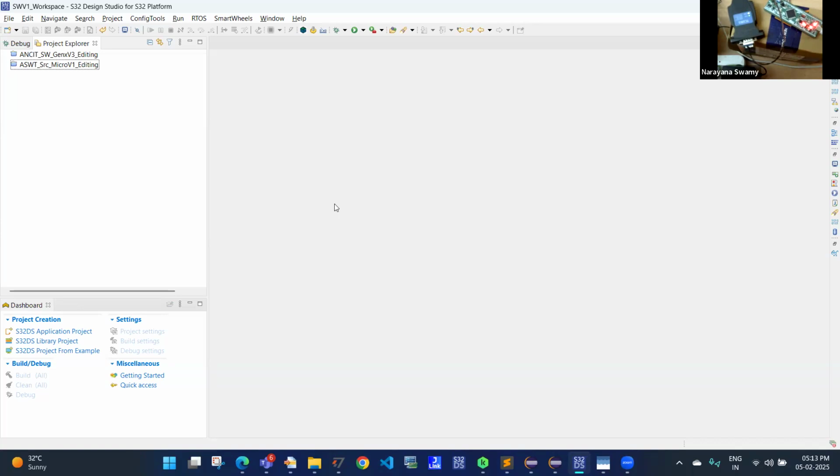And normally the example projects provided by any of these IDEs will be called blocking codes. Blocking code means it will do only one work. There will be a code for digital input, digital output, ADCs, PWMs, everything, where only that will work. If you start integrating everything, you will see that one of the code blocks the other one.